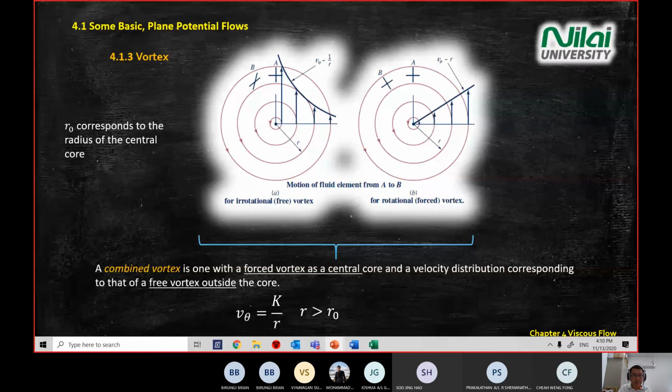So in simulation, if your simulation can give you an illustration of the vortex, normally they will give you a very small R. They won't put 0 as R. They will use R equal to 0.0001 in the calculation. So these are the limitations of the mathematical model when you're using simulation software.